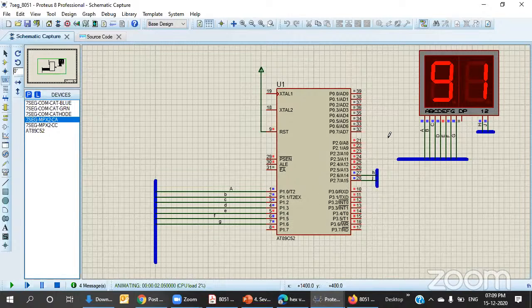Here it is only wire labels helping, not pins. Just remember this one. This is the process. If you have more connections, I don't want to connect all the connections, so in that case we will use bus mode in Proteus. Outside also we have one option. Some controllers have individual pins. Try the number format. I will check.